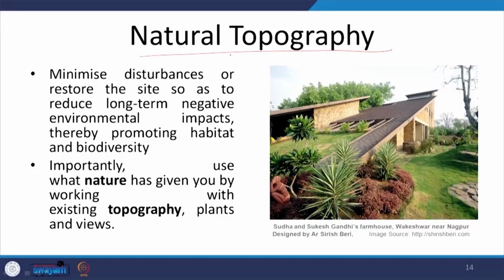So, with the help of creation of a small bund or a small boundary around the pond or the low-lying area, it will be able to hold all the water which will come running to it. And since it is not lined, the bottom of it will not be lined, so it will allow percolation. Now, the design feature here was, besides the engineering of not lining it or adding a bund or a boundary to it, the main point was topography and